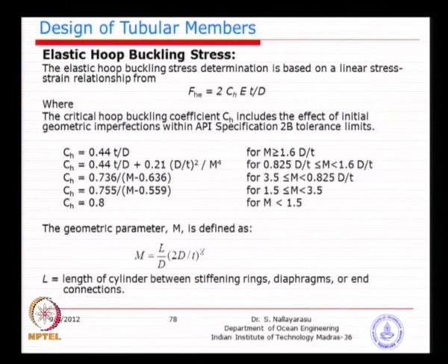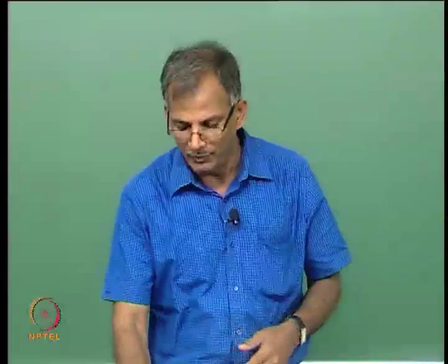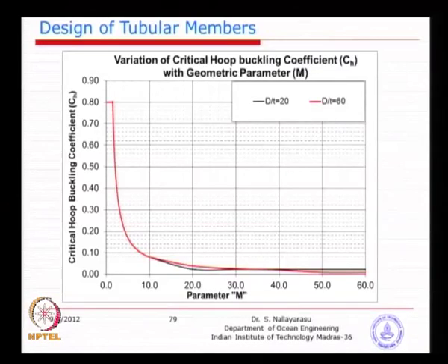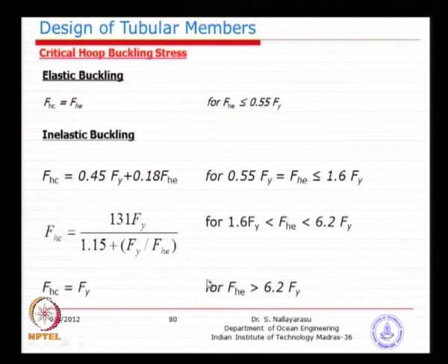As soon as the elastic stage is exceeded, it will form a wavy form, and the allowable stress will come down. That is why you see here the elastic buckling will be at higher stress, and elastoplastic will be going down. So, basically we need to use the elastic stress to find the elastoplastic or inelastic buckling, which will be lower than the elastic stress.